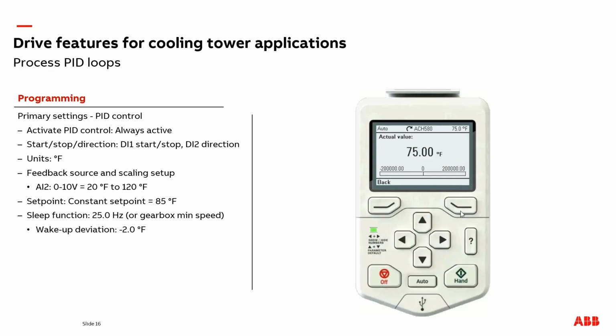I'm going to go ahead and leave it at a constant set point and adjust it here. For tuning, we'll leave tuning at the defaults for now because this is just a demo unit. That is where you would adjust it in a real life situation. For increased output, I wanted to increase the speed of the fan when the feedback gets greater than the set point.